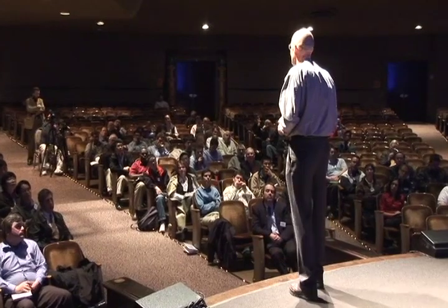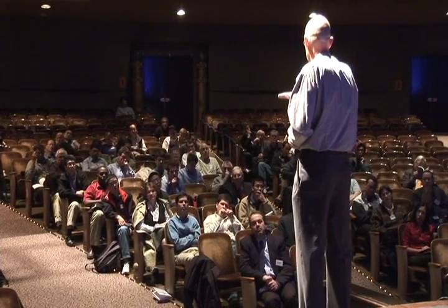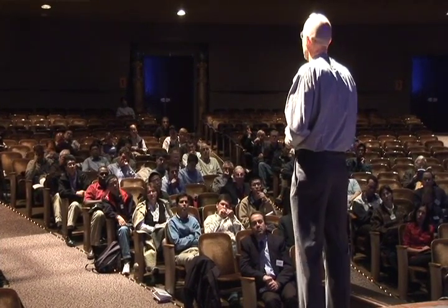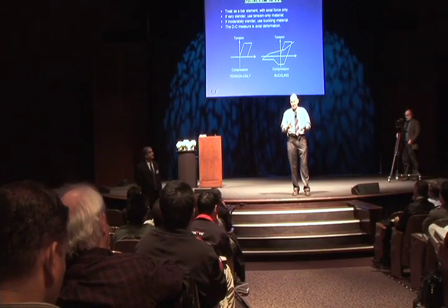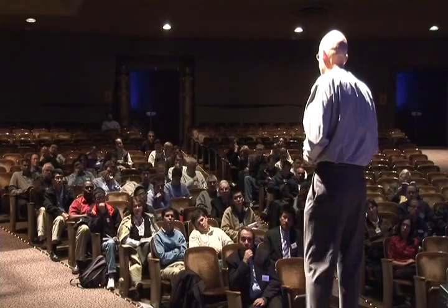And you can do one of two things. You can either model the internal framing directly, and you may want to do that even though it adds more elements to the model. Then you put the loads on the gravity columns, and you'll get the P delta effect from that, including maybe any torsional P delta effect which may be present. The alternative is not to model the internal framing, but now you must put in a special P delta column, where you put on that column all of the loads on the internal columns, and that will provide you with the P delta effect. It won't have any torsional effect, it'll only be the translation, but the torsional usually isn't that large. But the mistake is to leave it off. You must put it in.